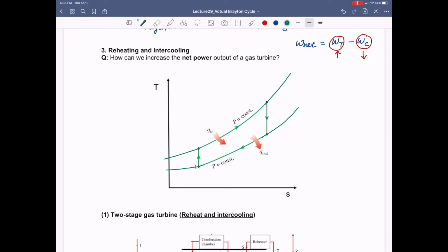So, graphically speaking, in the TS diagram, the gap, the distance between two curves here, like for the example from this point to this point, graphically represents qualitatively the amount of work produced by expansion if we go this way. In that case, this gap means the amount of power we need to run the compressor, and here the smaller gap is better.